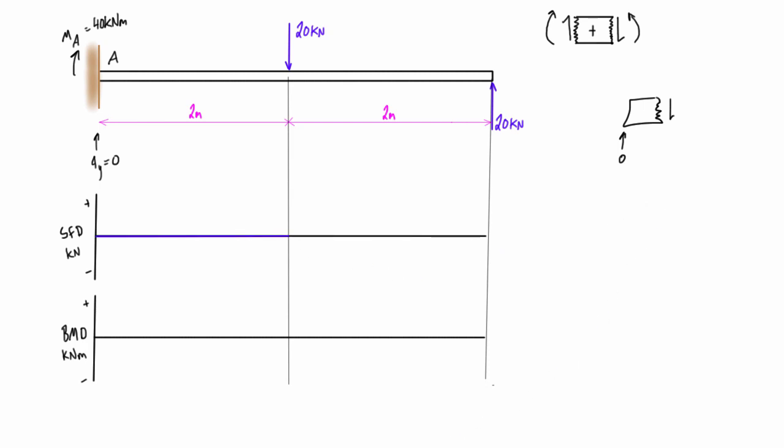Now once we extend a Freebody diagram just to the right of the point load, we have to include this 20 kilonewtons pressing down. So our Freebody diagram goes from the support at A to just right of the point load. That means we have a shear force of 20 pressing up, or negative 20 in the downward direction. A shear force pressing up to the right of a virtual cut is opposite our positive sign convention, so the sign is negative.